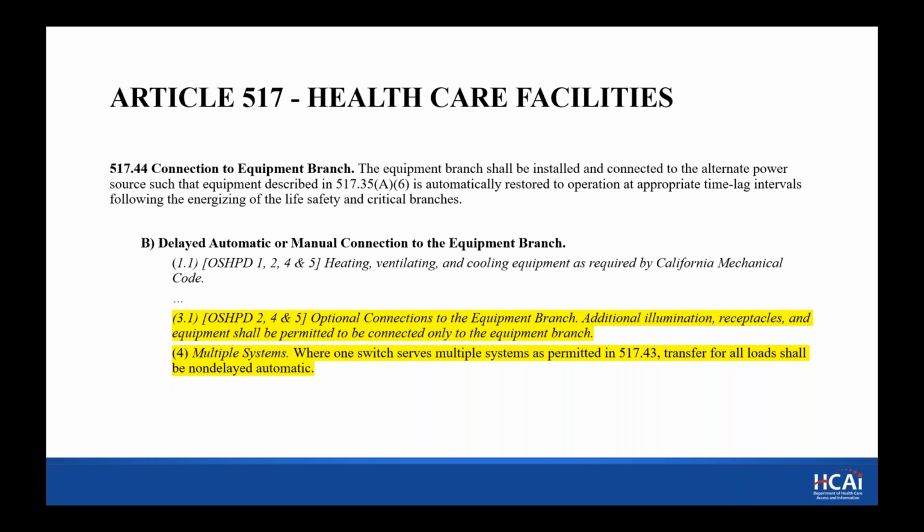Optional connections to the equipment branch are permitted, where one switch serves multiple systems because of the size of the generator under 150 kVA, then you would need to transfer all loads within the 10 seconds as required for life safety.